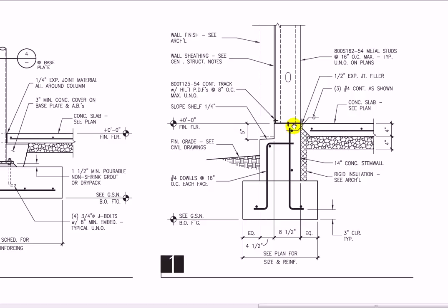On structural concrete drawings, these heavy lines indicate rebar. The size of the hooks are usually not shown because those are standard per ACI specs. So a standard 90-degree hook is what the contractor would give there unless there's a dimension shown. A circle indicates a rebar that we're cutting through, so those are longitudinal ones. So you can see in this wall, you can see this line here.